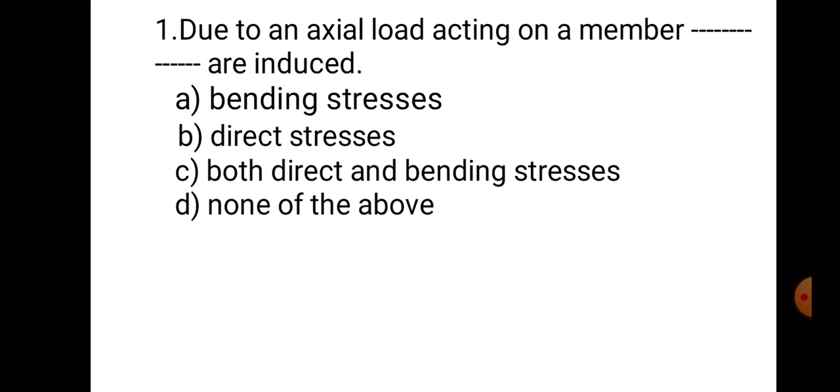Question number 1. Due to an axial load acting on the member, dash dash dash are induced. A. Bending stresses. B. Direct stresses. C. Both direct and bending stresses. And D. None of the above. Now in this question, the load given on the member is axial load, and due to axial load, we know that only axial stresses, which are also known as direct stresses, are induced. Hence, the correct answer is B. Direct stresses.